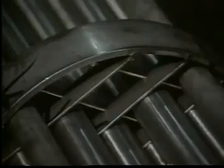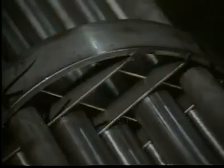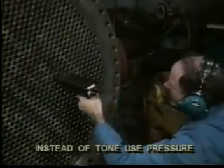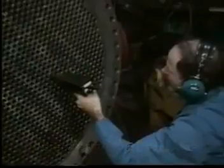In some exchangers, if sound does not travel to the far end, both ends should be tested. The tone may also be blocked by baffles or support sheets. If more sound is needed, you may use more tone generators with existing fittings in the central area of the heat exchanger. Or you may create additional fittings for testing purposes if your company's policies permit. In certain situations, it may not be possible to use the tone method. In these instances, use the pressure method.